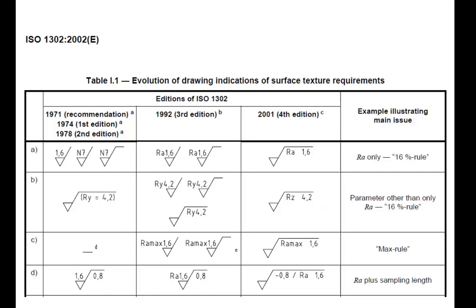In my presentation, in the lecture notes, you can find the conversion table. Instead of writing the roughness value numerically, write a code, an N code. The advantage of using N codes is that the reader can directly see which value it corresponds to. There will be no doubt whether the number written over here is the maximum roughness height or average of 5 regions or arithmetical average of roughness height.